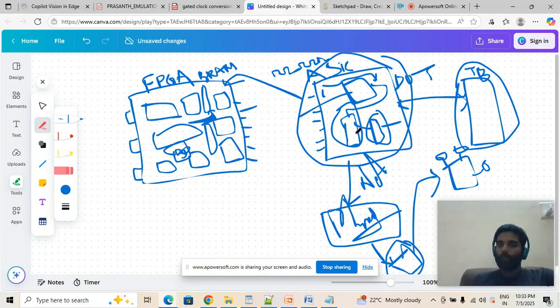And then we have these IPs, and these IPs are not going to be pure RTL again, right? We are trying to take them from Synopsys DesignWare IP or whichever tool you use. You're trying to use that IP only. So how do we replace this IP in the FPGA platform? We have to find a way. How do we replace these IPs in an FPGA platform? So these are the common things we should think about.